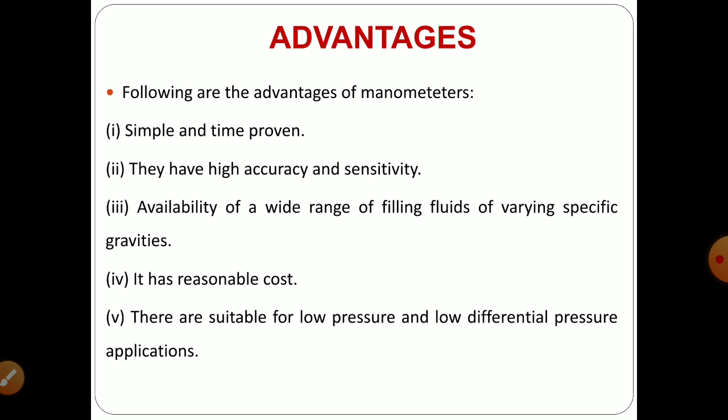the manometers are simple and that will give you result into the specific duration of time. At the same time, they are having high accuracy and sensitivity. The availability of a wide range of filling fluids at varying specific gravities will give you a hand to use manometer for the specific implementation or measurements of fluid flow. And as I told you earlier, they are suitable for low pressure or low differential pressure applications.